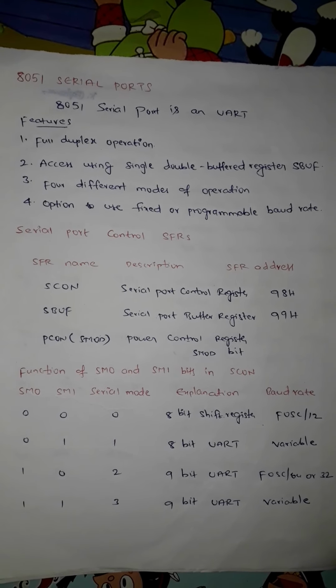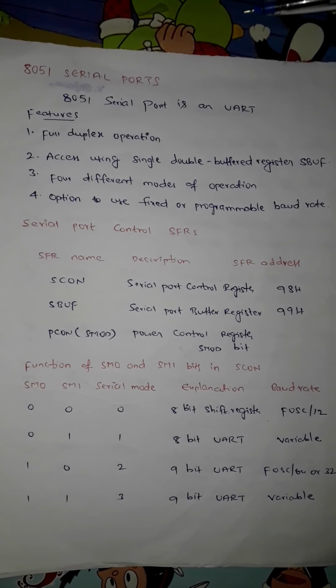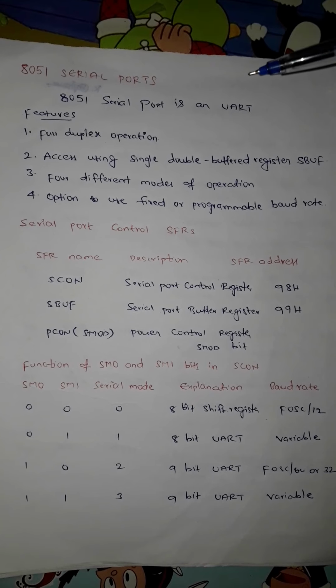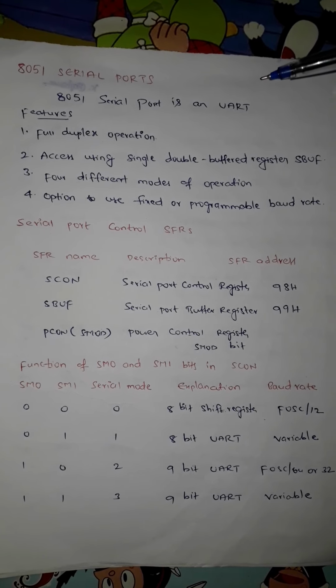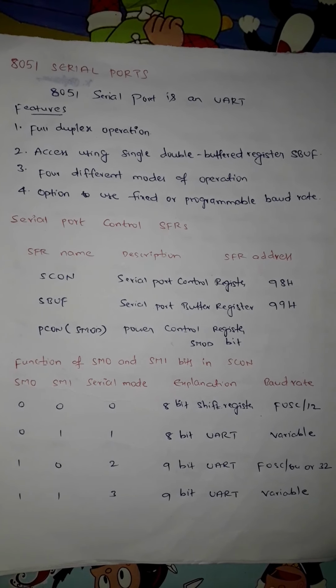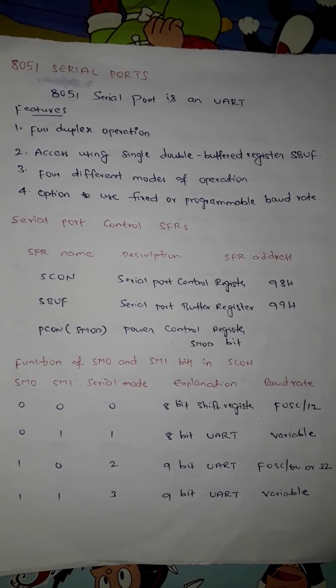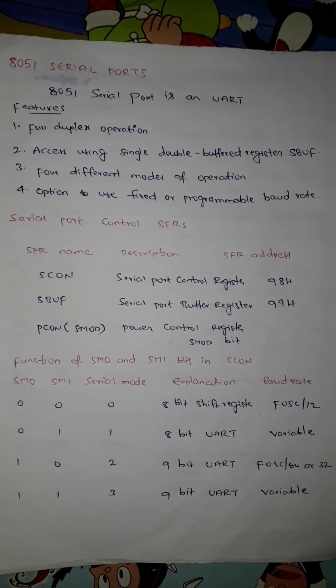Today in this video lecture I will discuss about 8051 serial ports. So the 8051 serial port is a UART device, that is, UART stands for Universal Asynchronous Receiver Transmitter. So you can transmit the data serially in asynchronous format, or you can receive the data serially in asynchronous format.